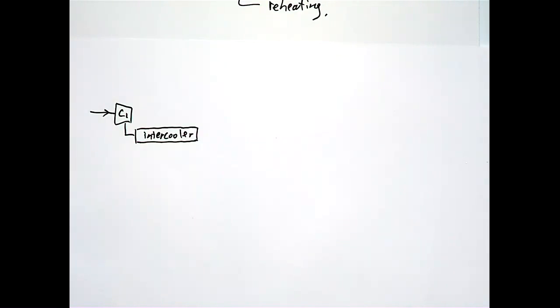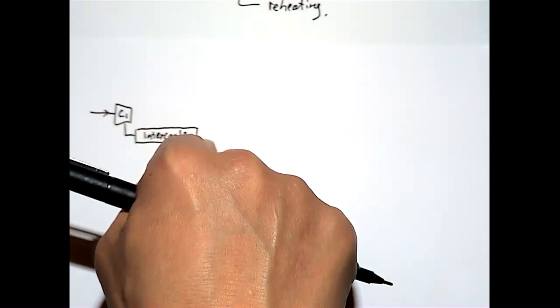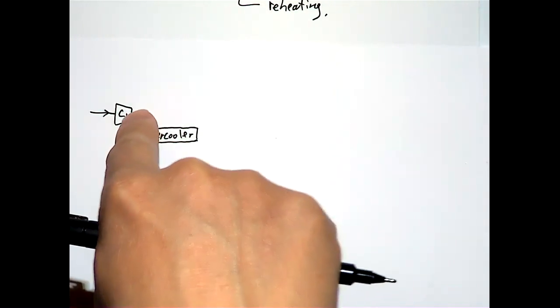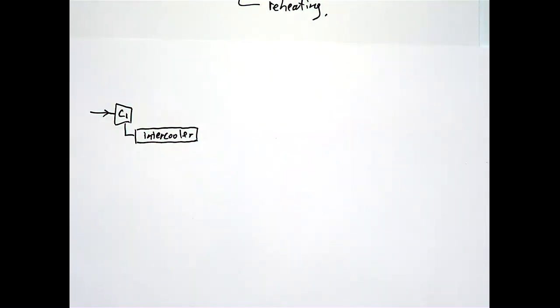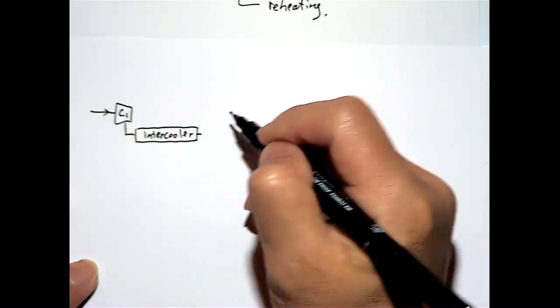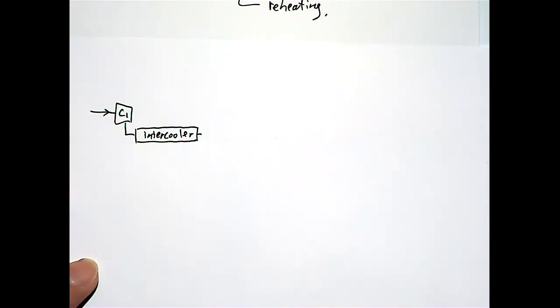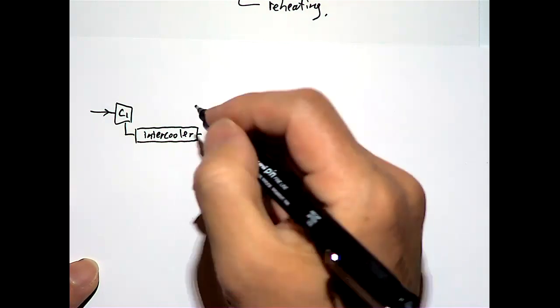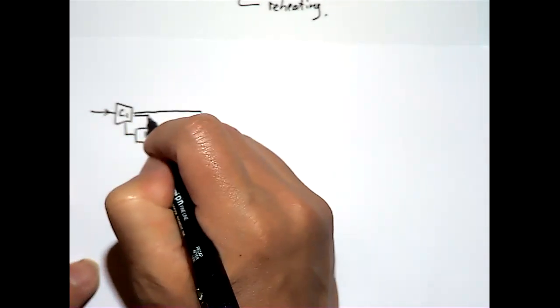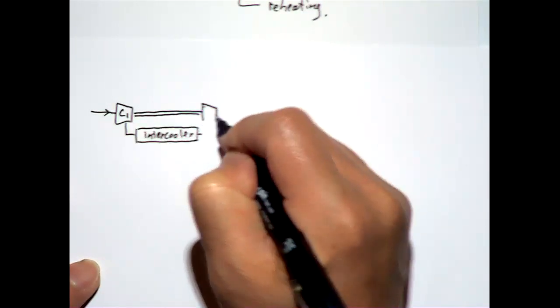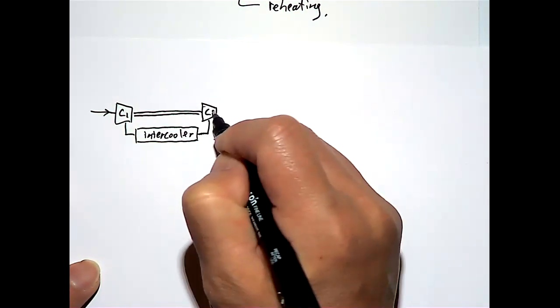You're taking heat out. Why don't you put that heat back in at the regenerator side? You could, but you've got a limit in terms of if this temperature is not hot enough, it does not help. It needs to be hot enough in order to help the compressed gas get to a high temperature. But that's a good thought in terms of utilizing energy, don't waste any energy. Yep. And then this compressor is connected to the second compressor. So C2 there.